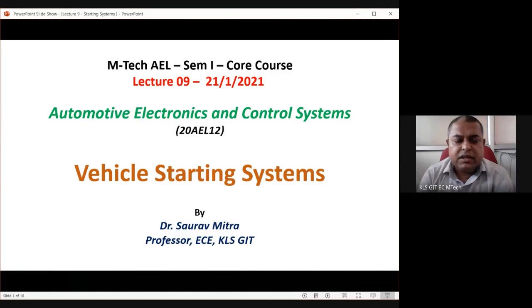We are going to start lecture number 9. This is the concluding part of the third topic from module 1. The third topic is the vehicle starting system. We have seen what a starting system is, what a starter is, what a starter does, what the different configurations are, and what the different types of motors are. That is the DC motor. Mainly we have said that the series type of DC motor is what we can use for the starting system in the starter. So whenever we say starter, it is actually a starter motor.